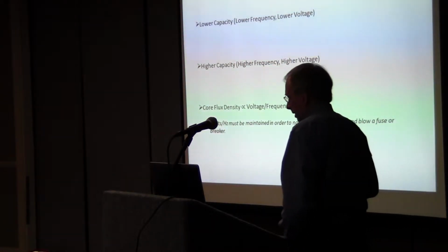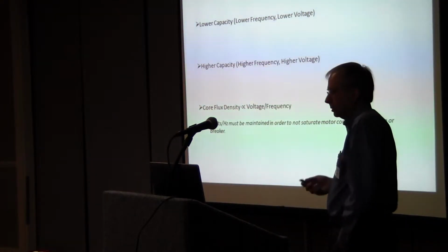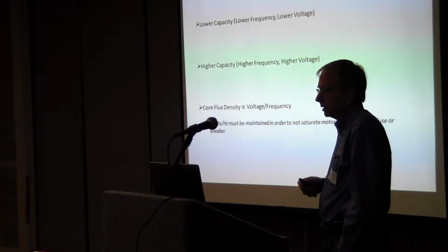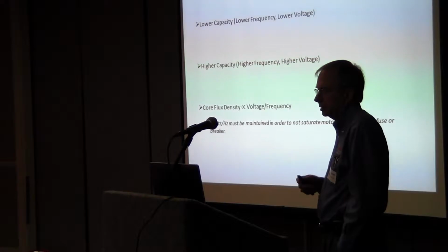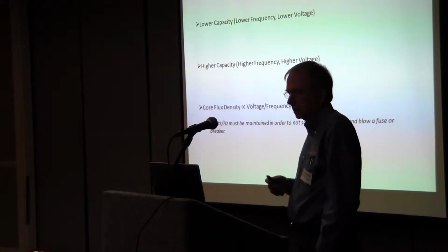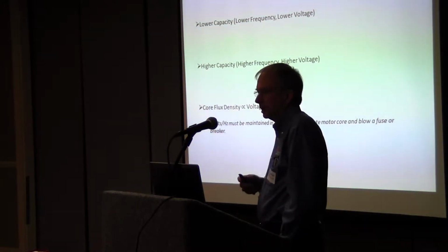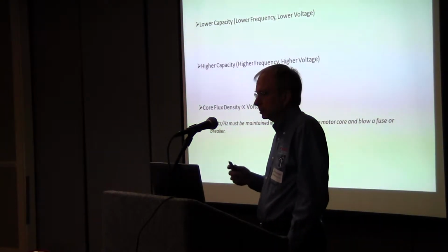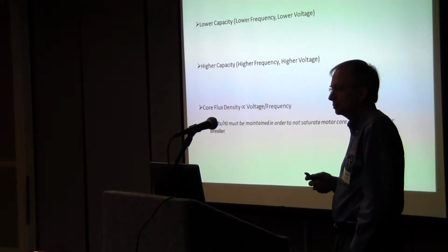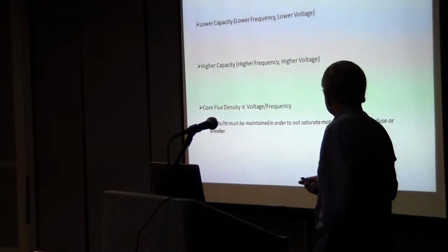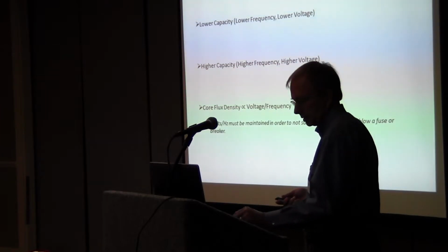Just kind of a side issue on the magnetic side. If you take a transformer that you bought for a 60 hertz application and decide you want to use it at 50 hertz, you have to reduce the voltage proportionally. So if you take a 60 hertz transformer or 60 hertz magnetics and you reduce the voltage by 5/6, then everything continues to work, not overheat and burn up. Another way of saying that is the volts per hertz need to be constant.